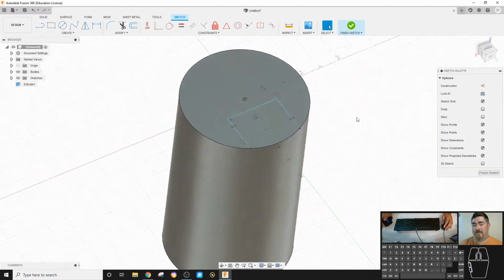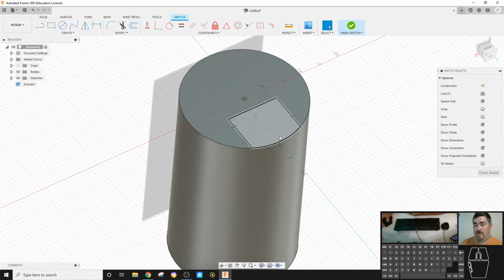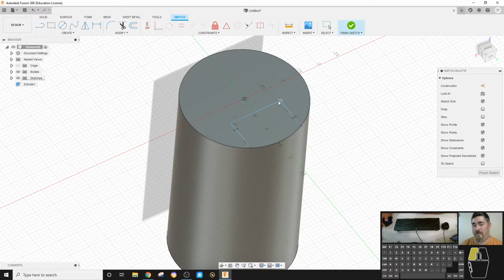And so this is kind of the steps. You create geometry. You use the edge of the geometry of existing stuff if you have it. If not, you go to the origin. You create your geometry. You add constraints so it behaves correctly. If you want it to be centered, it's behaving centered. You want it tangent, whatever.